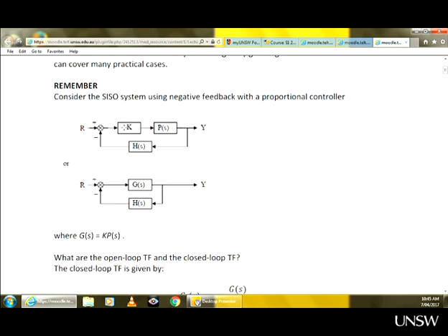Once again, if all poles are on the left-hand side of the s-plane, so either they are real and negative, or if they are complex, their real parts are negative, then the system is stable. So the system needs all roots of the denominator, called poles, to be on the left-hand side. If at least one pole is on the right-hand side, this system is unstable. So we are hoping that this negative feedback loop will push all our poles to the left-hand half of the s-plane.